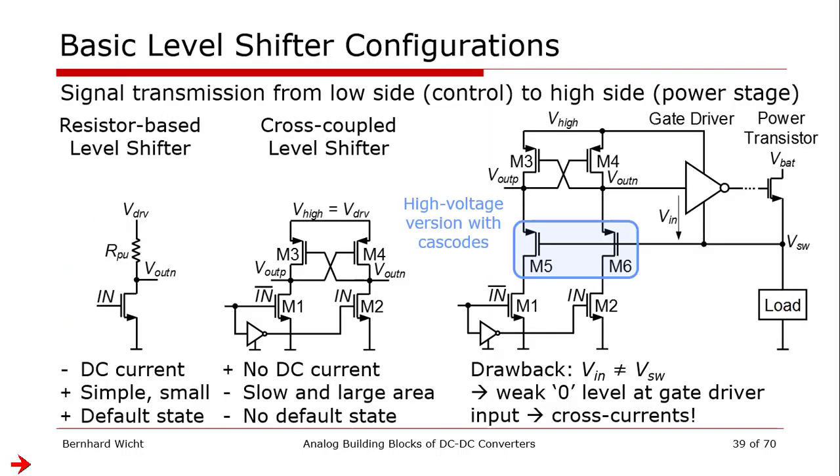So that brings me to the topic of level shifters. Level shifters we have looked at already. So we know the resistor-based level shifter and the cross-coupled level shifter, with some pros and cons. Especially for higher voltages, this cross-coupled level shifter sees the full source-gate voltage on these PMOS devices, equal to the gate drive voltage.